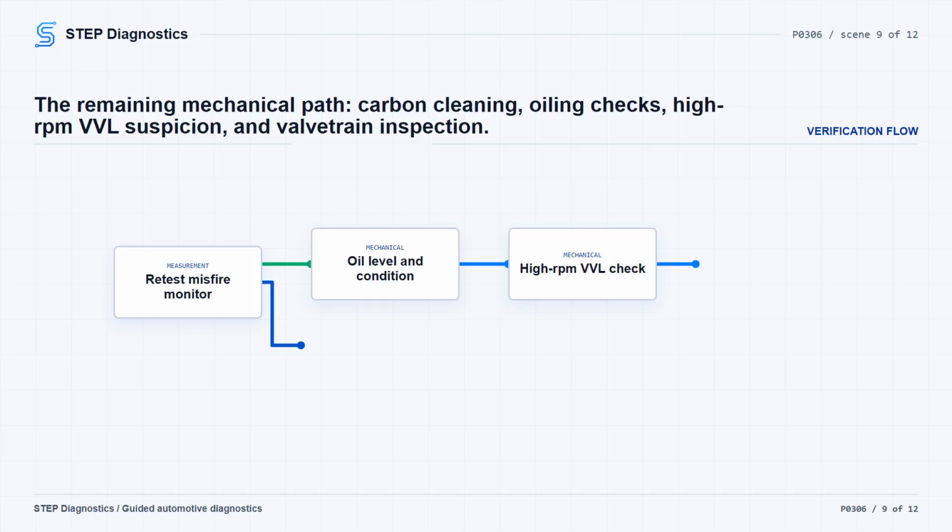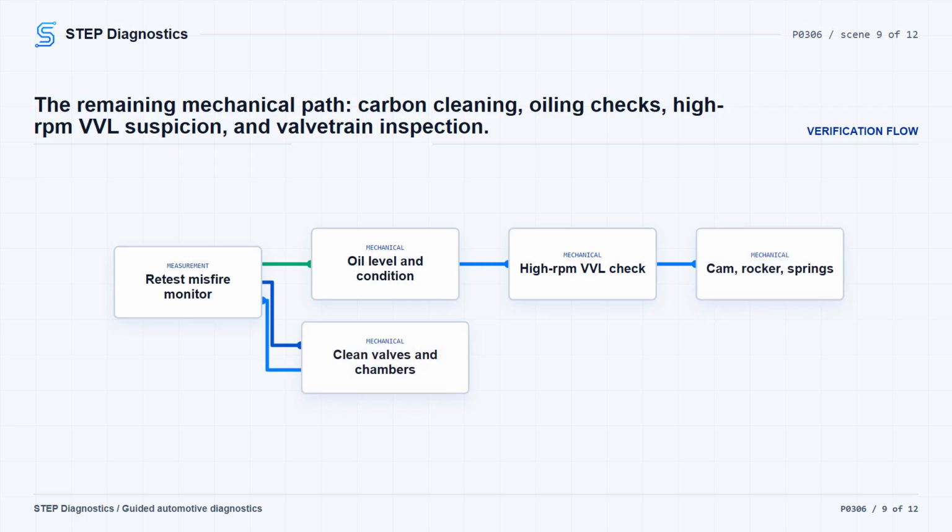Look for mechanical tolerances out of specification, oil pressure out of specification, low oil level, the wrong oil filter, dirty or deteriorated oil, contaminated oil, wrong viscosity, or aerated oil. Repair any oiling or mechanical issue that is found.